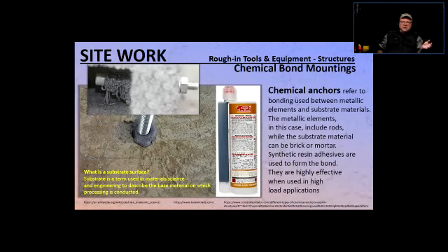In the previous video, this is a repeat of Monday's or yesterday's video, sorry, I had a situation where there was a bunch of brackets that was supposed to be mounted in the building to hang a bunch of old-fashioned TVs. So this was a few years ago, right? And the company who was doing that used some drop-in anchors, but they used them on cinder blocks. The cinder blocks were not sturdy enough to hold those drop-in anchors. They would work, they were just not holding as they should have been, right?